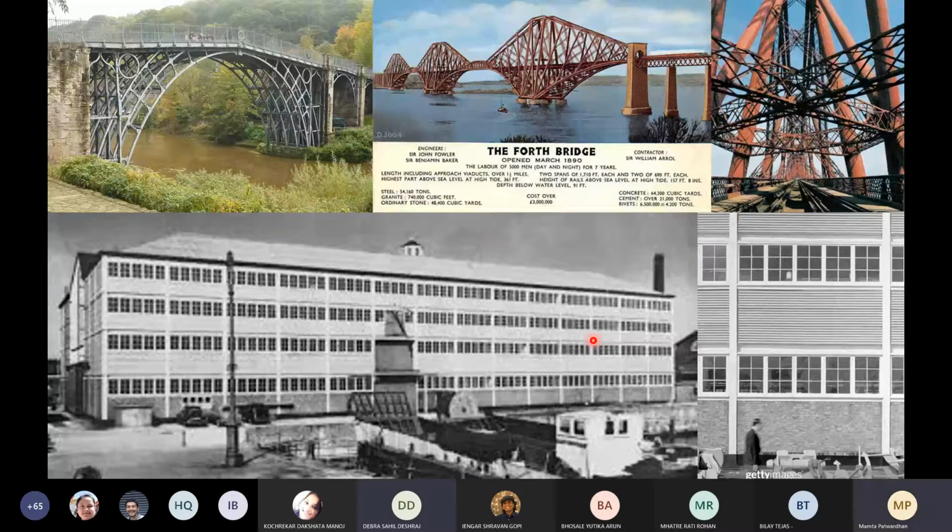Now in this case, you have cast iron columns, you have beams, they're supported, the beams are timber joists, you have wrought iron plate girders, and they're spanning 30 feet. So each bay is 30 feet. So this is very similar to a portal kind of a structure, what you would call today a portal. Okay. Did you get that? Can we move on?